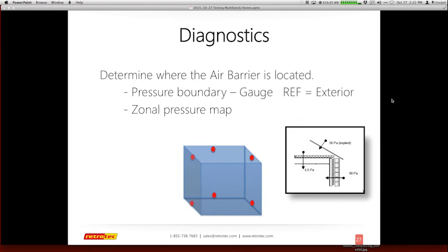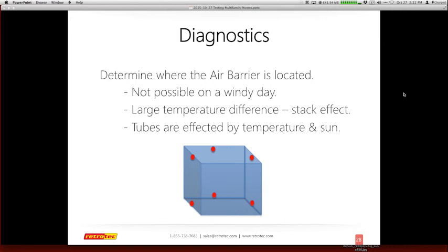So we recommend a method where you're testing the boundary high and low. Those are your best way to get a good pressure map. That helps me determine whether I have issues that are only on the bottom side or top side, or where my pressure differences are. Sometimes that can be challenging if you have some type of fire stopping framing in between them. But in general, if you're going to check one spot, it's great to go around a room and create a basic pressure map.